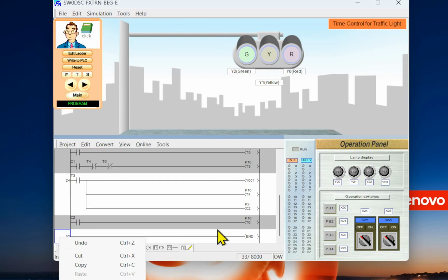The counter runs until the last number. For me, I use three, and it counts to 3. It's still 3. If you never reset it, the value is still 3, right? If you need to run a new cycle again, you must reset the counter to 0 again. This is very important.